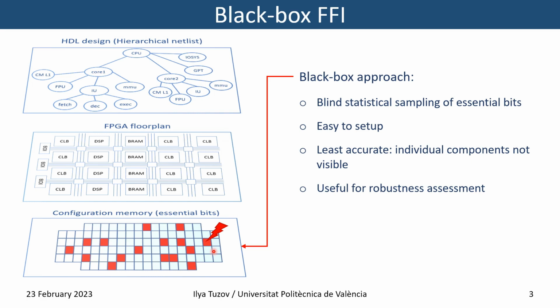Location of these essential bits is reported by Xilinx Vivado tool when generating the bitstream. The problem of this approach is that it does not provide any visibility of individual design components. As such, this approach is useful mostly for the robustness evaluation.